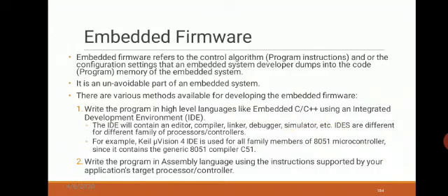Then IDEs are different for different families of processors and controllers. So suppose ARM uses Keil, Texas Instruments kits also will use Keil, and they can also be used with Code Composer Studio. So different platforms or different processors and controllers work with different types of IDE. Okay, for example, the Keil MicroVision 4 IDE is used for all the families of 8051 microcontroller, since it contains a generic 8051 compiler, that is C51.